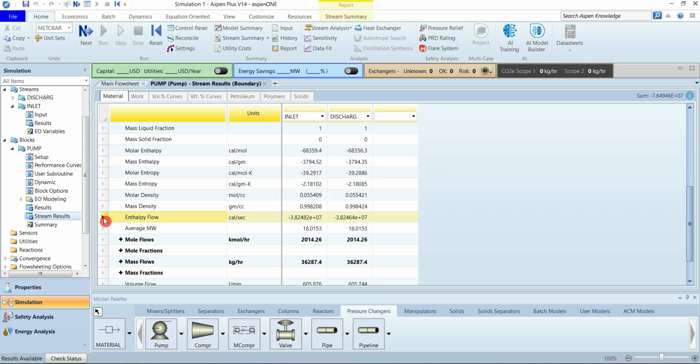You can notice the enthalpy flows are in the minus. Otherwise, generally in commonly available stream tables, you can notice a positive magnitude value of the enthalpy flow or the specific enthalpy. Aspen Plus assumes total enthalpy as a sum of the formation enthalpy as well as the sensible heat required to raise the temperature from the standard conditions where the enthalpy of formation is considered.